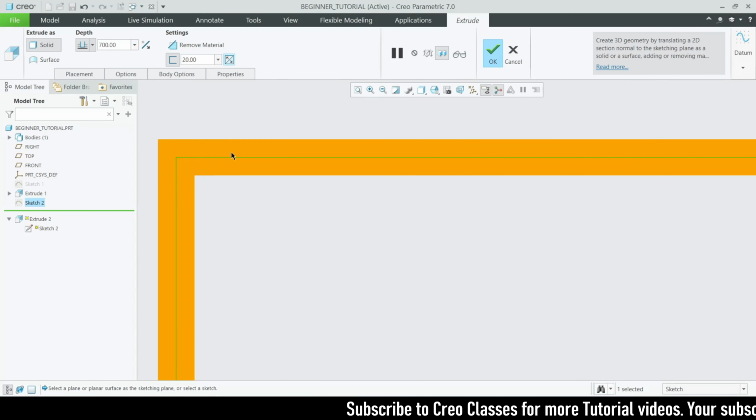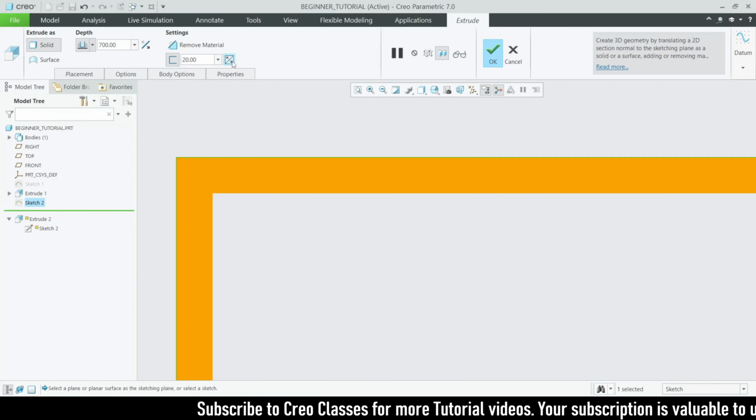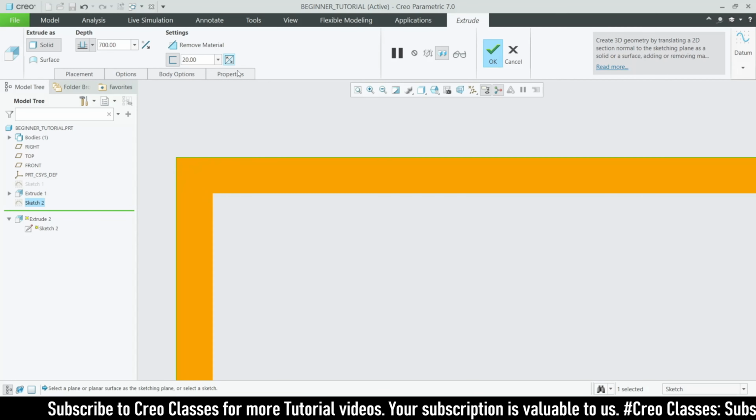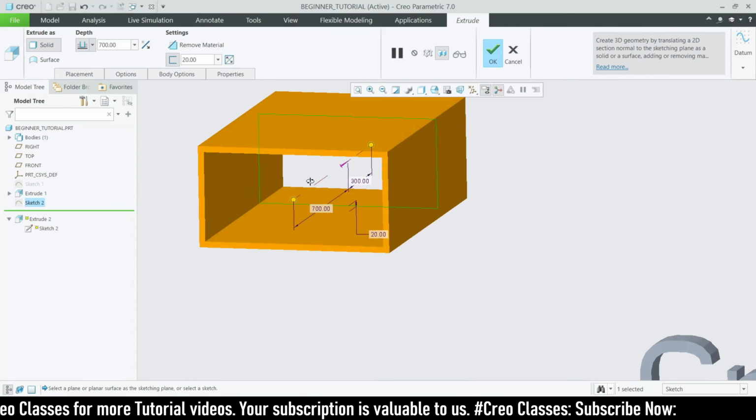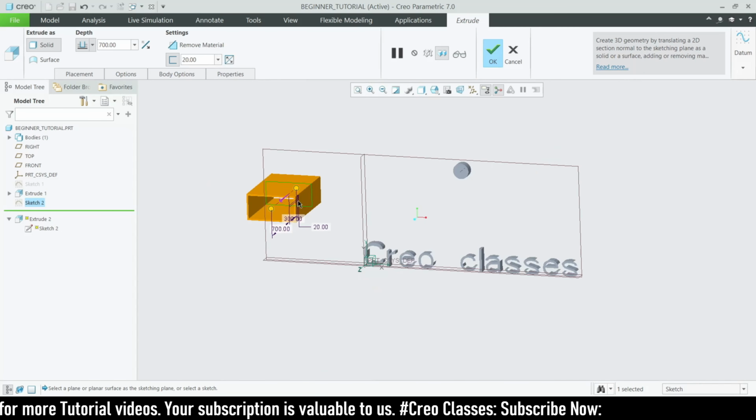Now you can see this line, right? If you click on this, the extrude will happen on the inside. If you click again, it will move towards the outside. So this is how this entire extrude tool will work. That's all, so let's click on OK.